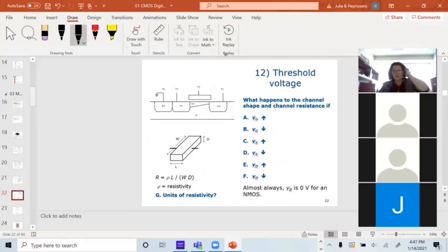Now, we want to look at this. I've got 3 voltages that I control. The body is generally tied universally to ground in NMOS transistors. In the lab, when we draw these transistors, we're going to use the 4-terminal devices. You are going to have to manually tie the bodies down.